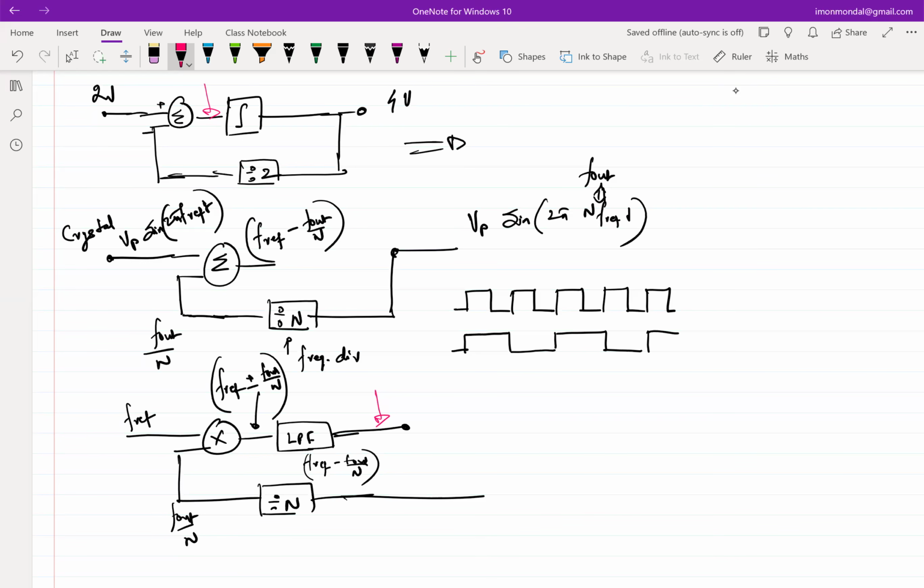Now with this integrator, we are in the voltage domain, kind of. Because we have a DC output, there is no frequency there anymore. Frequency of 0, we have a DC output. So you put an integrator. Then the output of the integrator has to drive the final output, but in this case, we cannot. Ultimately, the integrator output is a voltage which will keep on ramping if the input to the integrator is DC. But as Dhruv pointed out, we need something at the output to generate that final waveform of f_ref times N. So this is a voltage.